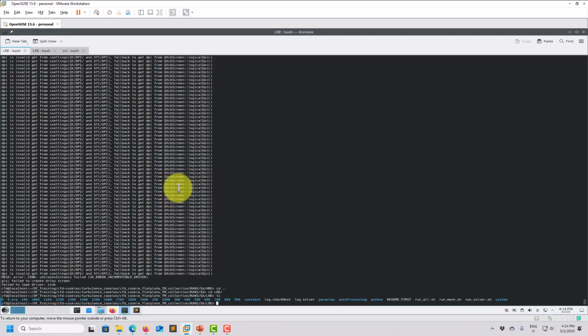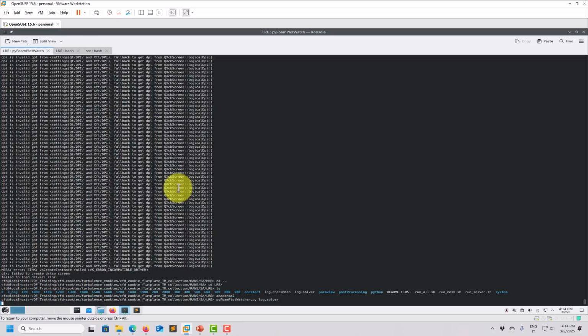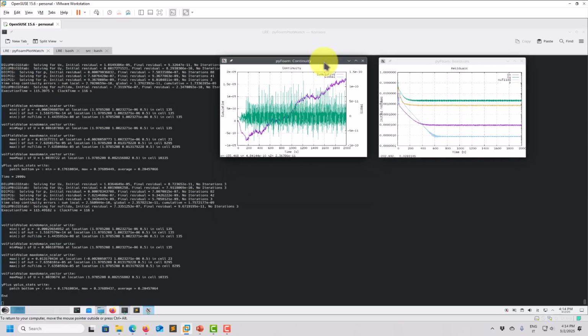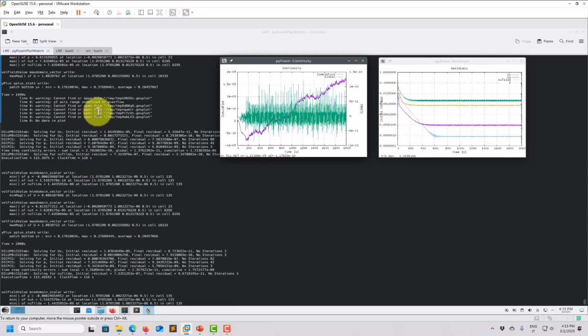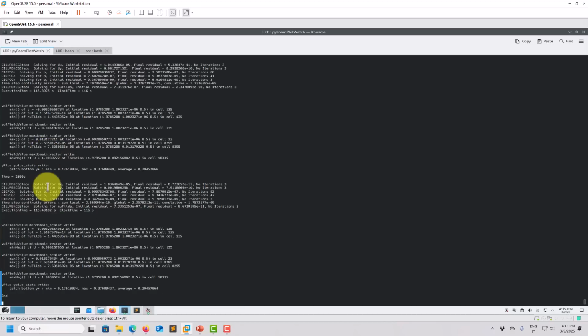So in the low rate, I'm not going to run, I already have the solution there, and let me just launch Anaconda just to show you in this case, Python plot washer log. So we have the log file, and look at that, perfect solution. Okay, nothing strange, the quantities remain bounded. Then here you have your Y plus plot, so wall resolving, no problems.